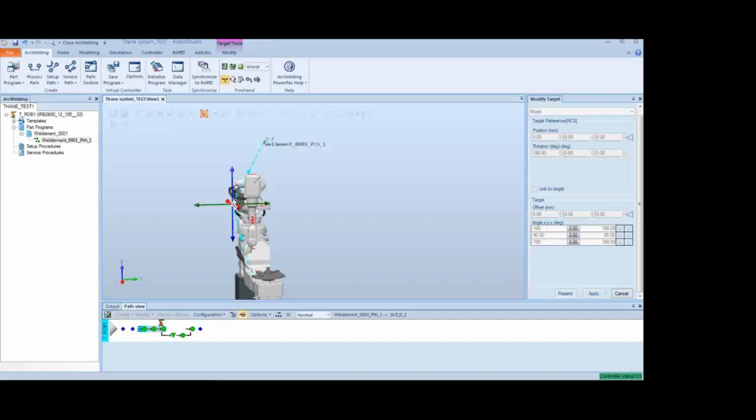To change a joint move to a linear move, select the target and hit the Move J to Move L icon that's above the target. And then move through the instruction to make sure all the motion looks okay.